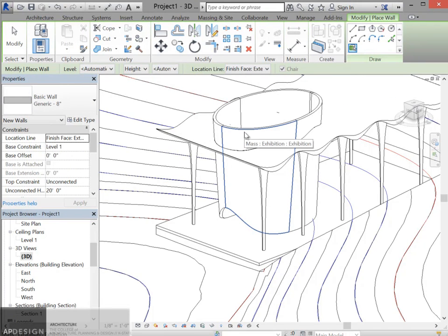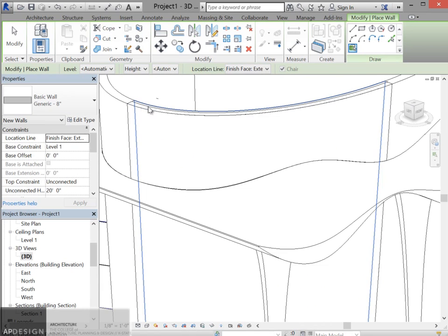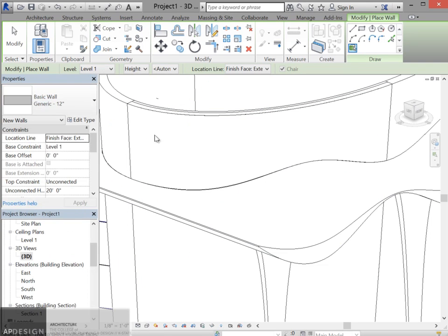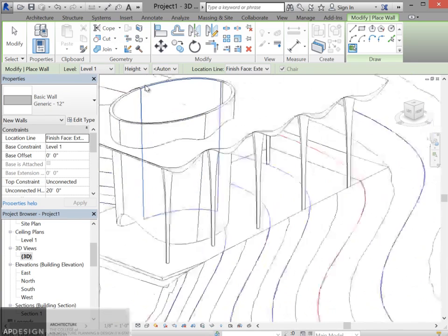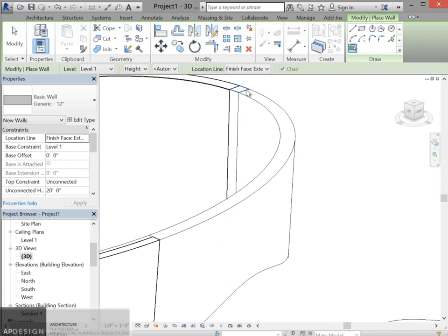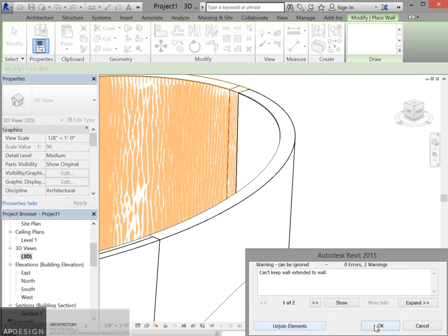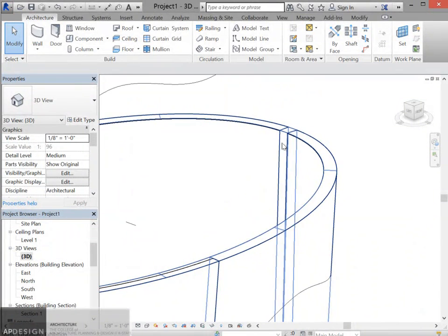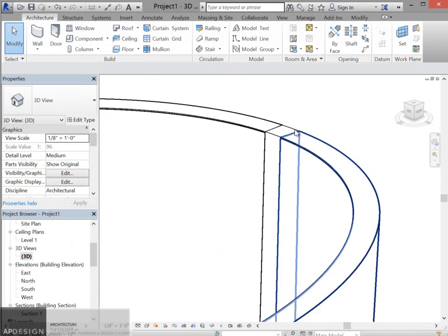So if you have that situation, of course you want to create a Revit form. I'm just going to click on the outer surface, and you might notice that now it's not quite as thick. It kind of has a line here. That's because I have a generic 8-inch selected. I'm just going to go generic 12-inch and create the rest of it using the correct one. And to make sure that I'm always on the outer surface, if you tab when floating over something, it'll select through various objects that you're floating on top of.